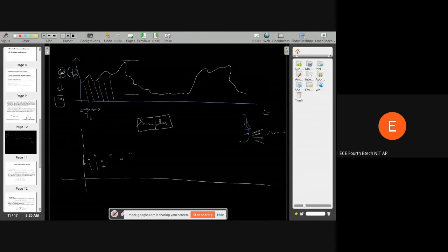We'll get a signal which has amplitude only at discrete times, only at certain intervals of time. This could be infinite, but it is not continuous. So if you sample the continuous time signal at a particular interval called the sampling period, we get a discrete time signal. We represent this as a sequence of numbers n, and we write it as S[n]. If S(t) was your continuous time signal, S[n] will be your discrete time signal.